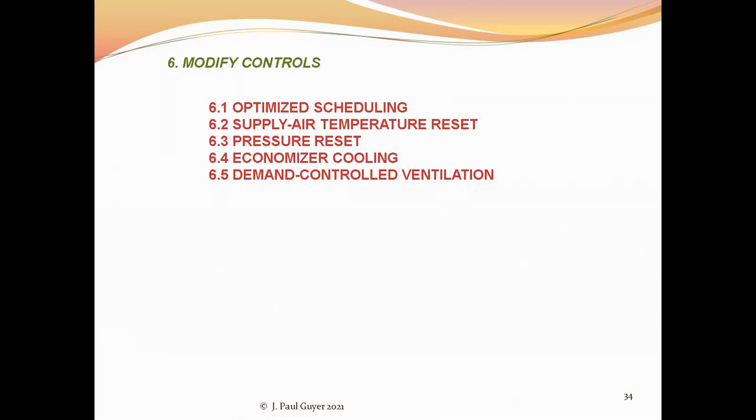And so when you have that condition, you can turn off fundamentally your cooling system, your chiller, if you will, and through this control system, exhaust 100% of the return air to the exterior environment, and draw in from the exterior 100% outside air for your supply air.